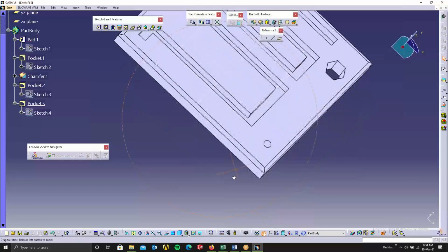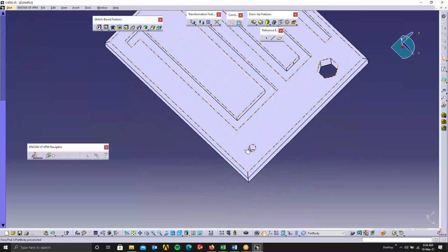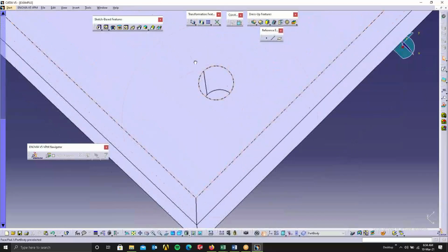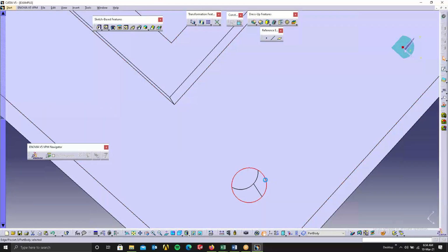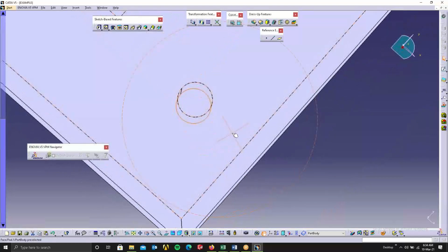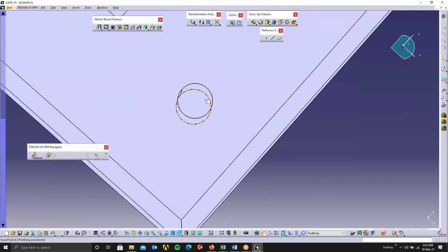Then here you can see a circular hole. This hole they have given a flat base. All normal holes have a V bottom, because all those drill tools have a V bottom. Here it is a flat bottom. So they have to drill to a certain height, then use another tool. They have to buy another tool called a reamer tool, and using that reamer tool they do this finishing. It'll take again close to 1 hour.